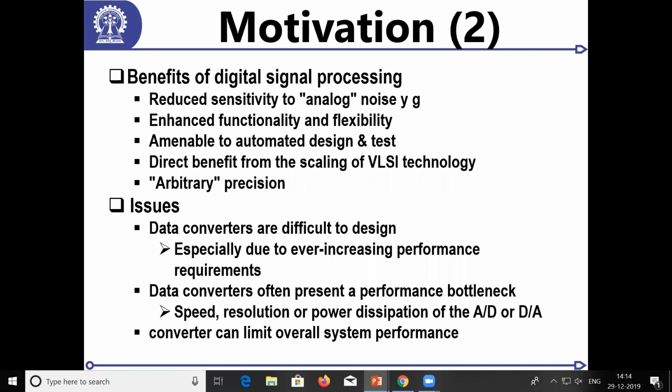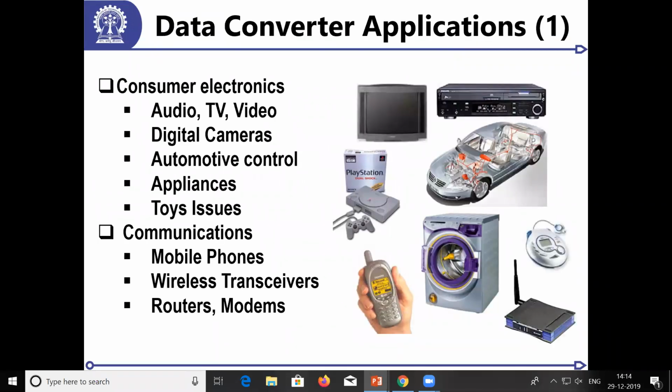How does it happen? I compromise on speed. So I do some kind of filtering and some other techniques, and I can get 16 to 24-bit resolution from a 1-bit signal. Almost all of the CD players in the world use that technique. You can go and open up any CD player, it will say 1-bit ADC. And your headphone is 1-bit.